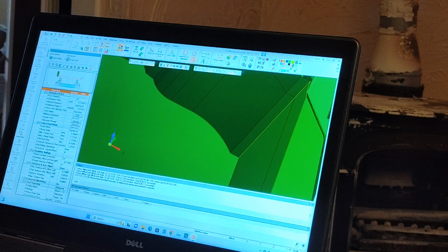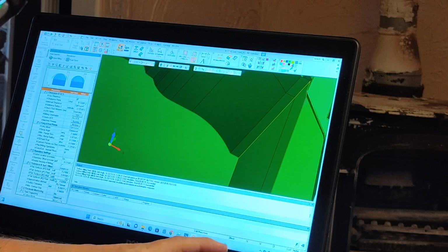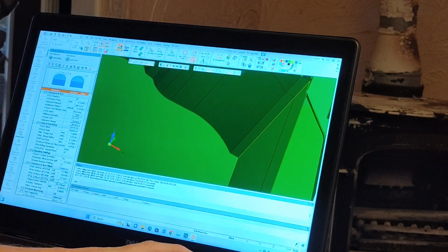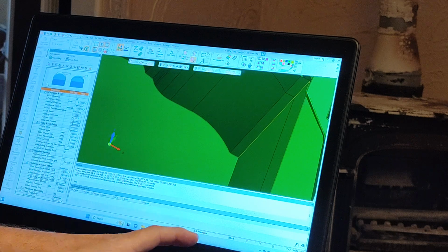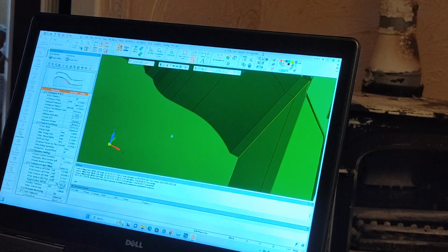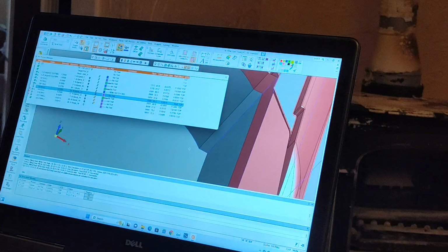So let's do this. We're going to switch to advanced for the surface offset. We're going to be 10 away on the walls, 10 away on the floors. And for that second group, we're going to go 0.035 on the walls and 10 thousandths on the floors. Let's see, make it. Yeah, that should be fine. And then save and calculate.